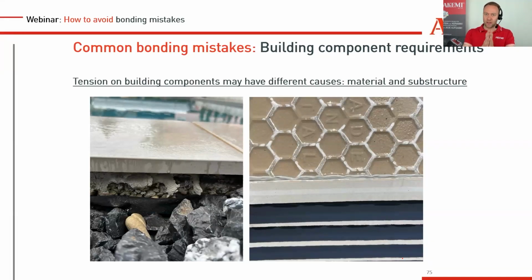Some natural stone, some materials, you saw the wood earlier, but it can also happen with stone and with ceramic. They have a tendency to bend when they come in contact with humidity, especially from one side, or heat. Especially when the heat comes on the top and it's cool underneath.